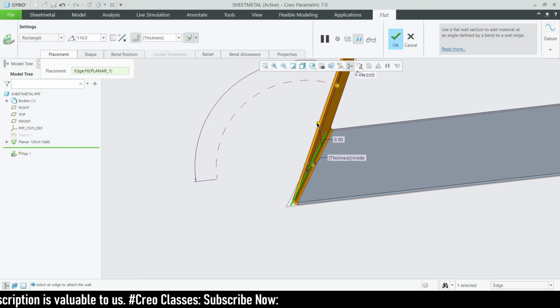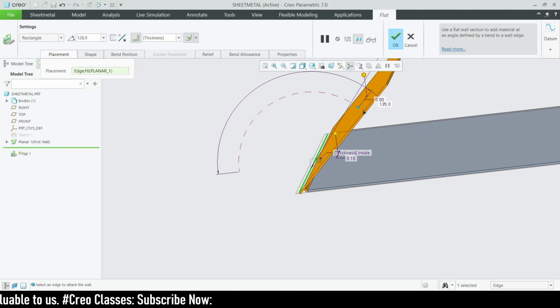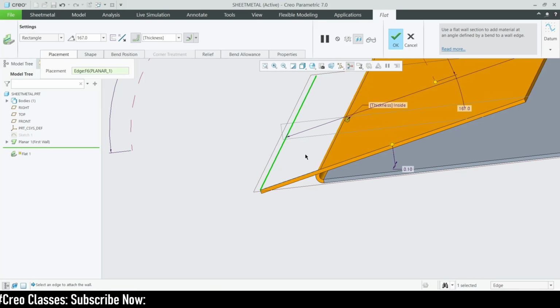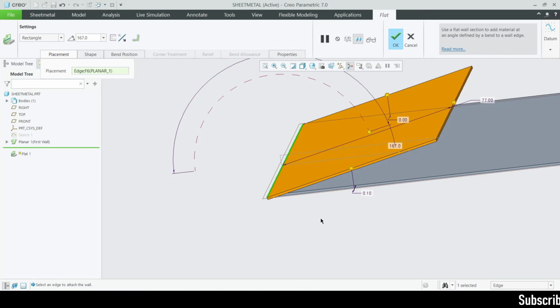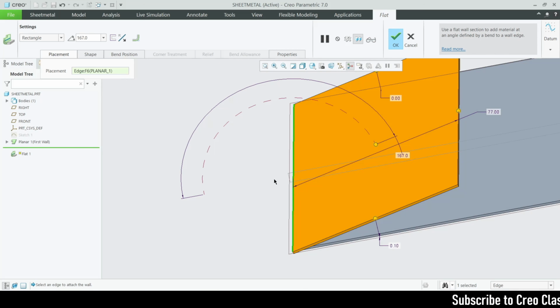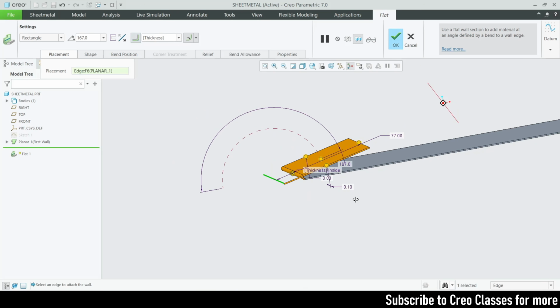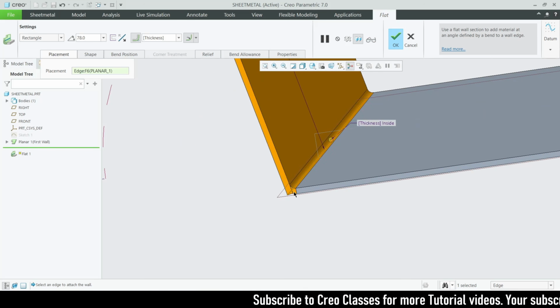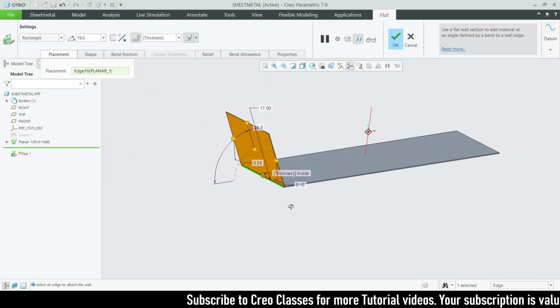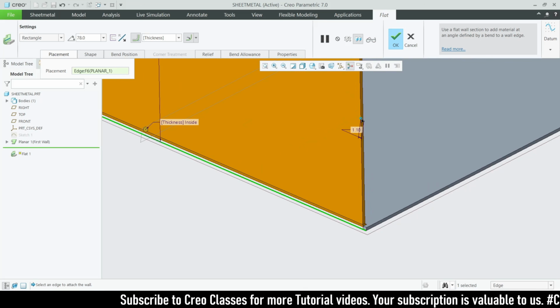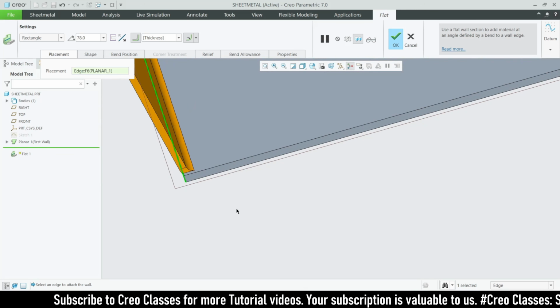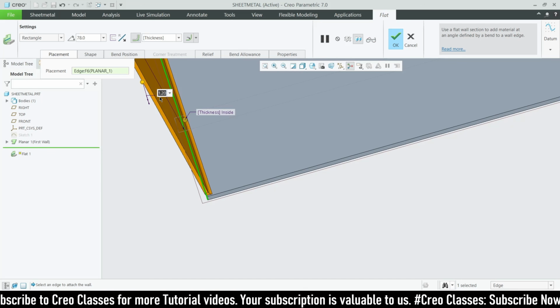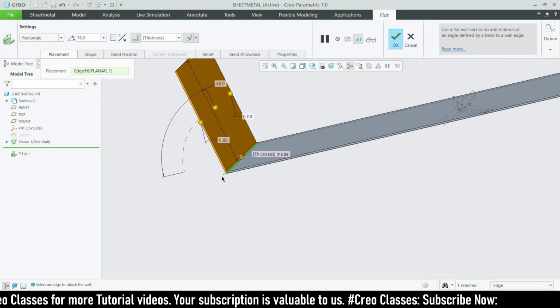For these cases, if you need to bend up to this, you can see the first plate has been decreased, the size has been decreased, right? So for that they will use this tool as a sharp edge. So now you can create the surface. This is what I mean. Let's keep it like this, and now we have bend in here. Let me just reduce this. Yeah, so we can have this as a 0, for clear information.